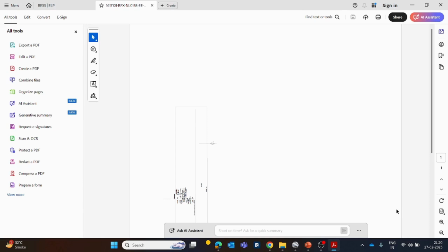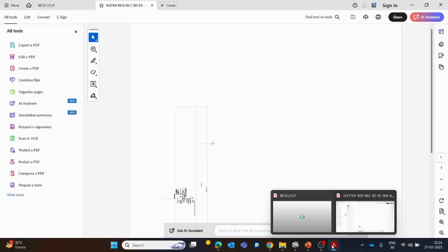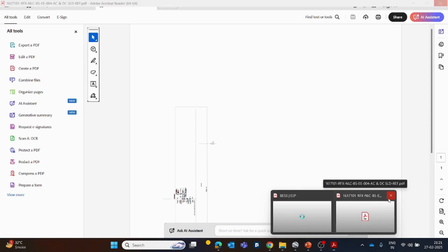But it might not be the case in BESS projects, because many times you can have containers with battery as well as inverter. And if it is only a battery container, then you might have a compact substation where you already have inverter, transformer, RMU switchgear, everything hooked up, right? So you might have to do only DC cable sizing there and MV cable sizing. And if the inverter is within the battery container, then you might have to do only AC cable sizing. DC may not be required, right? So the concept needs to be clear. If that's clear, then we are pretty much good to go.